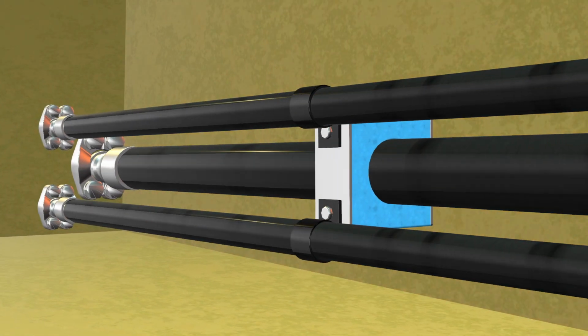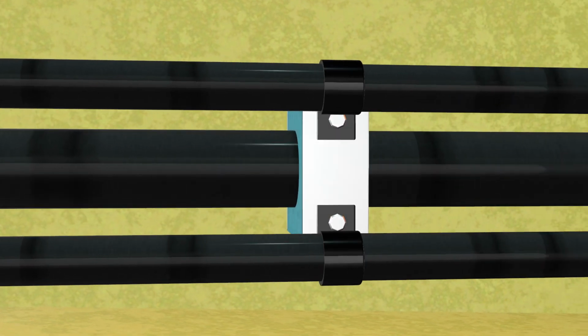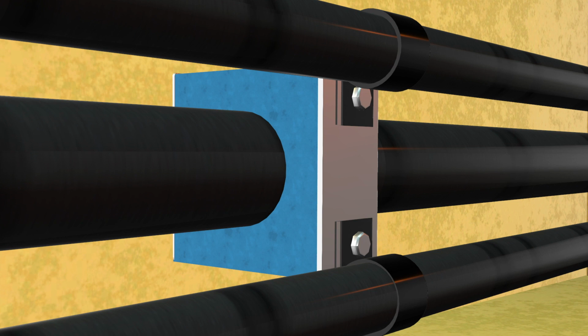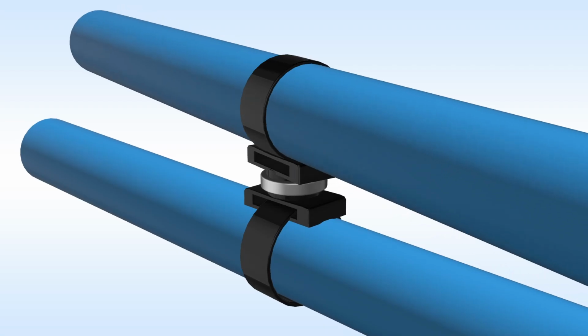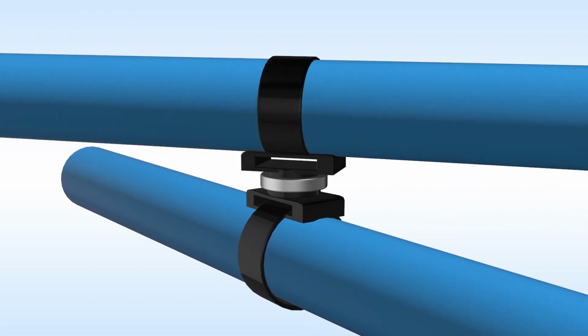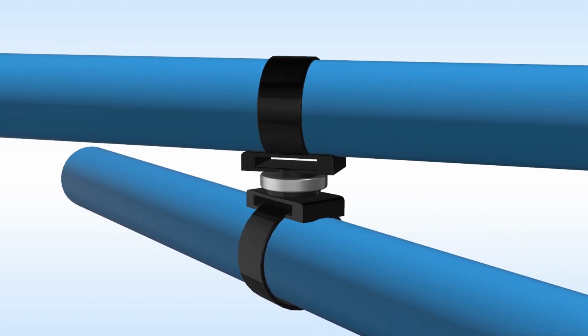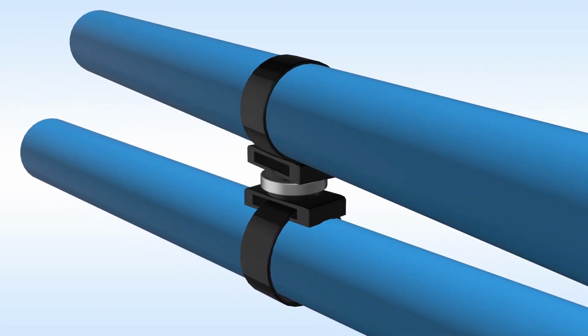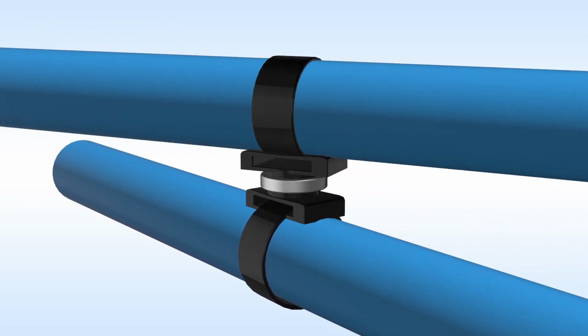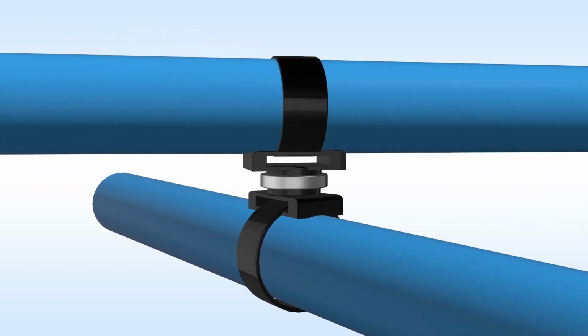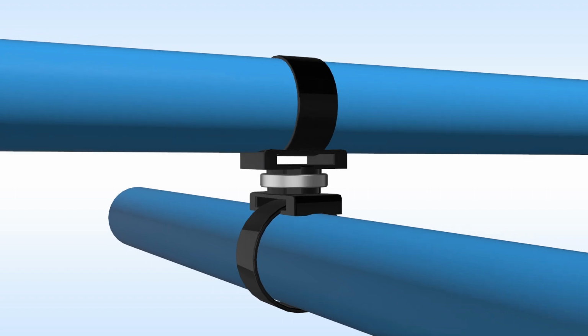Hose segregation. The use of P-clamps is helpful for segregating hoses so that the outer cover and braids don't wear away. Another way to segregate hoses is with the swivel saddles or rotating clamp. These are great as they physically hold the items that you are trying to segregate off each other, and as the name suggests, they swivel. So they work even if the hoses aren't in line with one another.